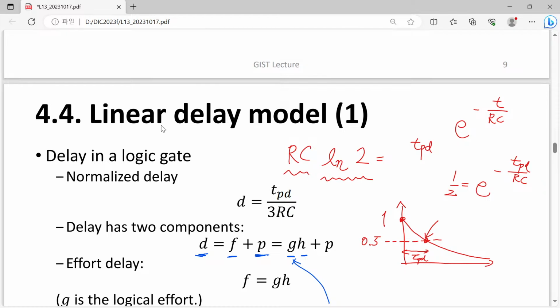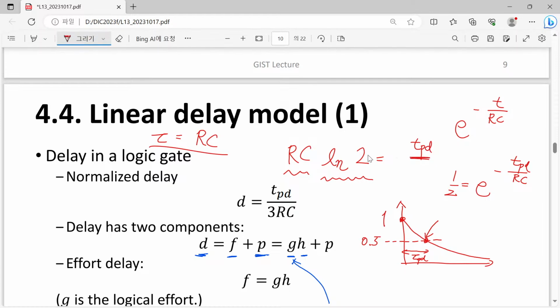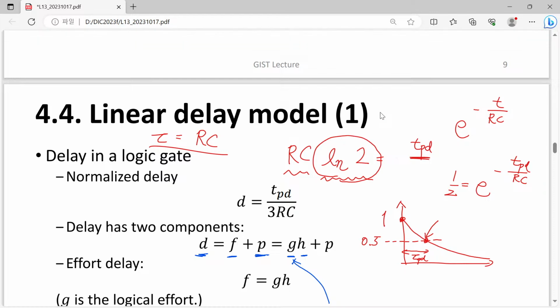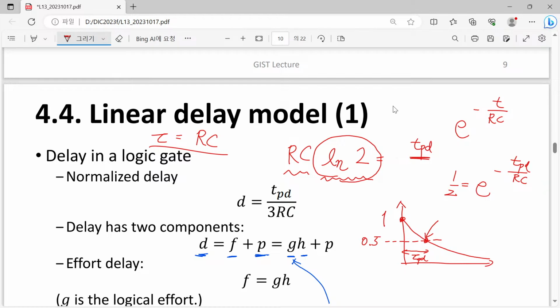However, what is our single time constant approximation? We just say that if we have an RC circuit, then tau is RC. So even in this simplistic case, our calculated RC and the real propagation delay are different. But not that much different, because the coefficient is close to 1; they are in the same order.